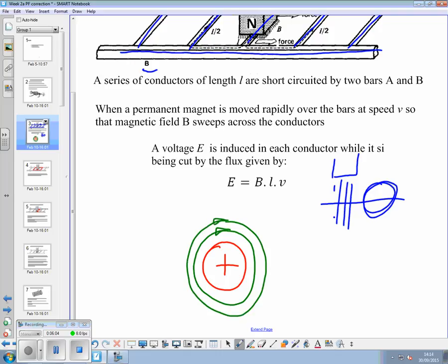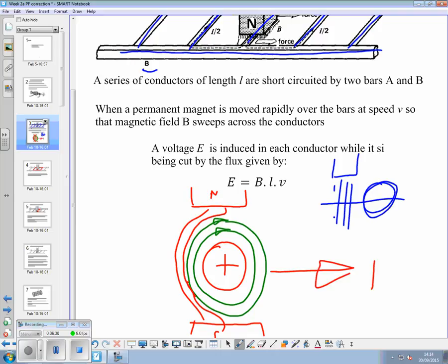like so. We've then got our field from the magnet, north-south. One of the properties of magnetic field, magnetic lines of force, is they won't cross each other. So what will happen is, this field from north to south here will go round that conductor to get between the two poles and effectively force it or pull it in that direction if it's free to move.